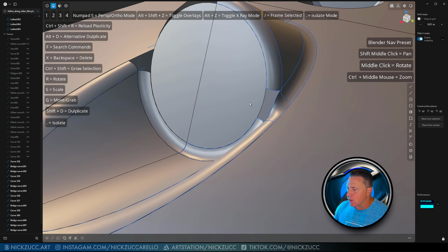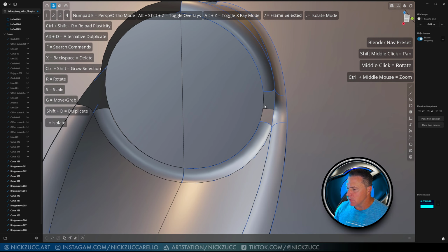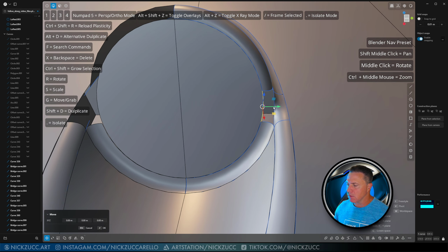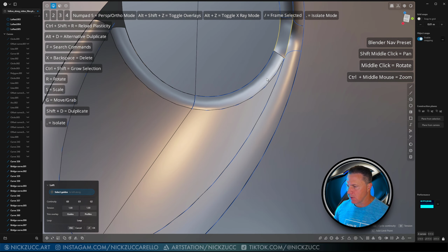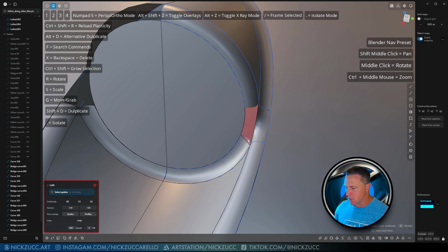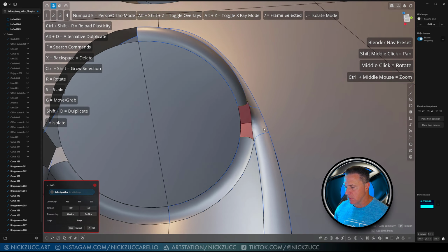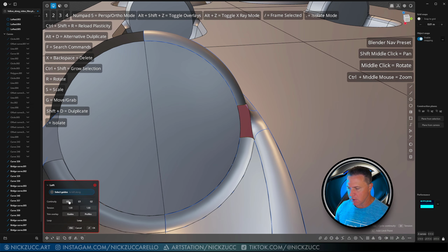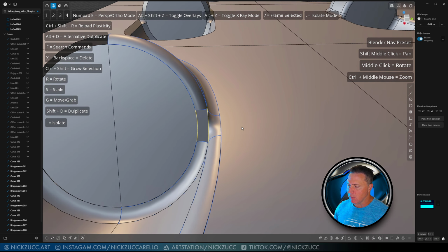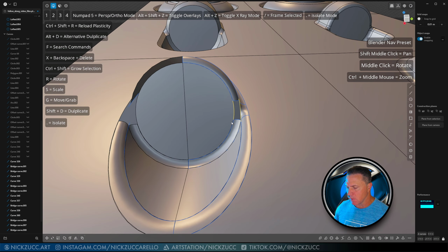So I could do another loft over here on this one. Let's select this and this, Shift D like that. And so we got this curve and then this curve right here. I'll tap L for a loft right there. Hold down Shift here, and you can see it's going to fail on us like this, no matter what the tangency is and everything. So this is what I was a little bit concerned about.